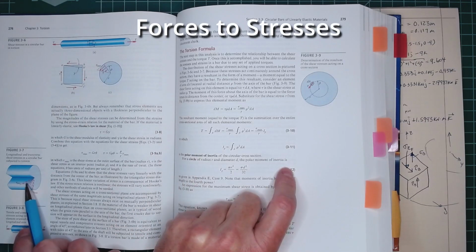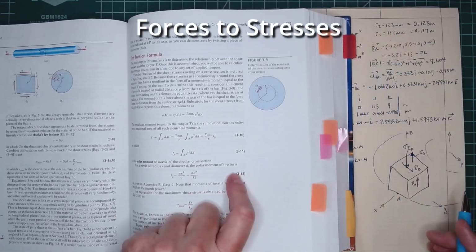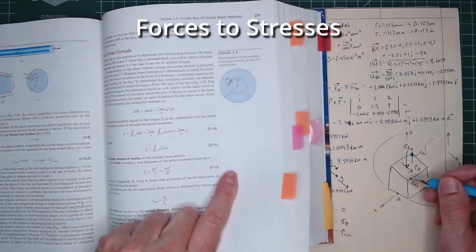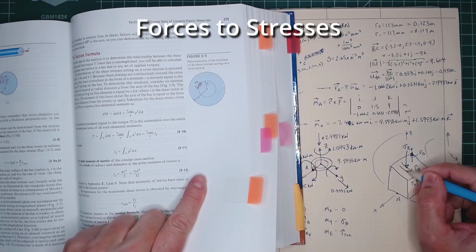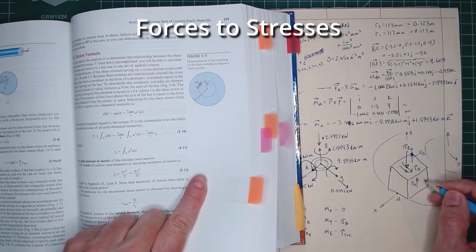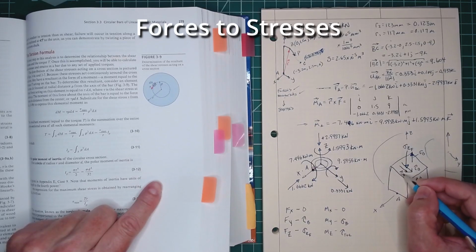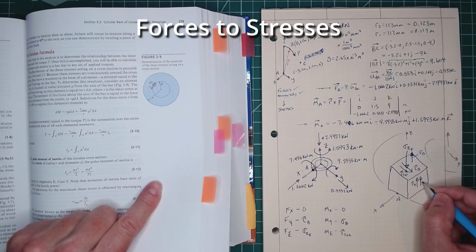They're only on the inside faces. So actually, this stress due to our torsion is acting on this face right here, again in the same direction as our other shear stress that's acting on there. So we've got our tau torque acting on there.